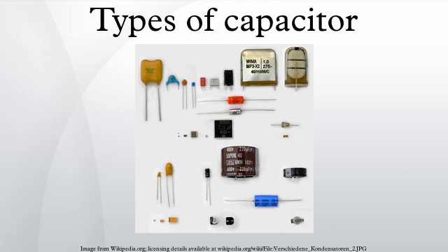If the inductance is small, the dissipation factor can be approximated. Capacitors with very low losses, such as ceramic Class I and Class II capacitors, specify resistive losses with a quality factor. Ceramic Class I capacitors are especially suitable for LC resonant circuits with frequencies up to the GHz range, and precise high and low pass filters.